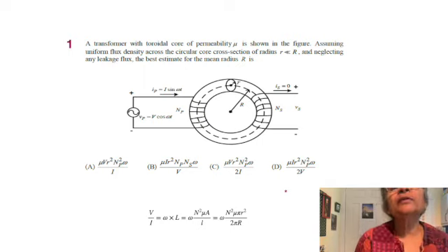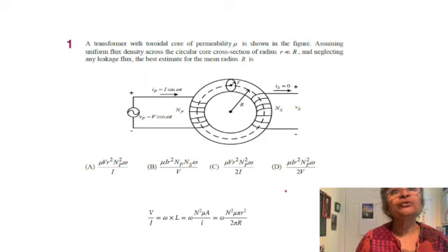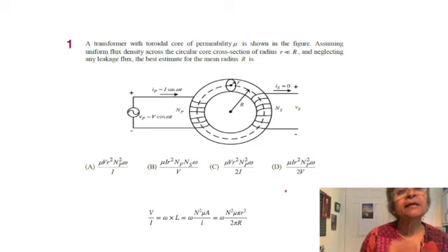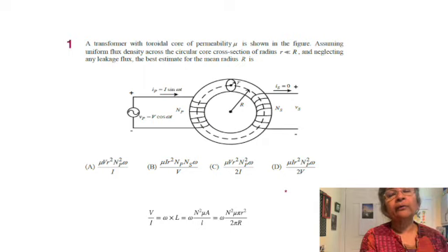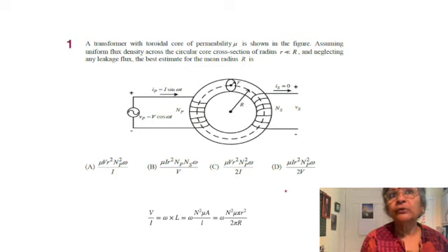And what is the effective reactance? It will have its own self inductance and also mutual inductance if it is possible, but in this case there is no mutual inductance because the secondary on the right hand side is open circuited, so we have no current flow through there, which if it was flowing would have caused a flux and so mutual inductance. So there's no flux and so there's only self-inductance.